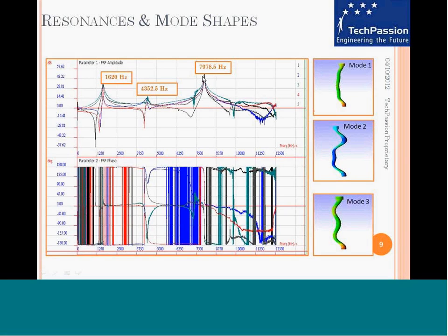So far we have not addressed the idea of defects. We are only establishing the methodology. So we take a part, we did simulation on that, then we followed this up with impact testing, and we are looking at these frequencies. Now, the question to ask is, what parameter will you look at to be able to tell the defects, which could really vary depending on the process. But in this case, we are able to identify some parameters which are able to clearly segregate the good and the bad.